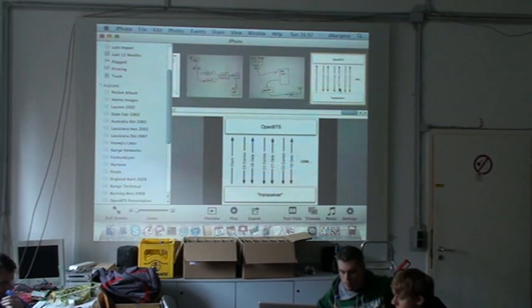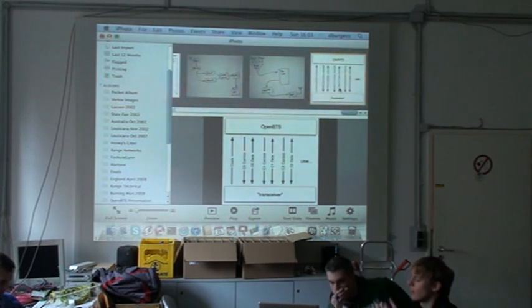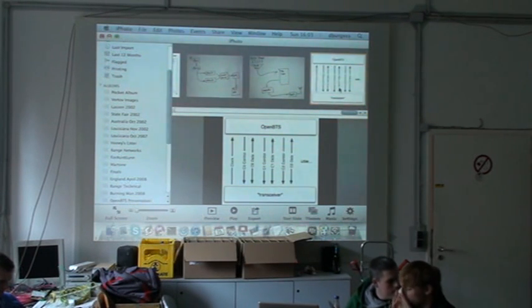No, there's throttling up in OpenBTS to prevent things from running too far ahead of real time. On transaction-driven channels, that's not so much a problem because we implement blocking writes. Writes into layer 1 are blocking. The write doesn't return until the burst has been sent across the UDP interface to the radio. So they tend not to run ahead of real time. But yeah, some channels have to be throttled back. So that's it.